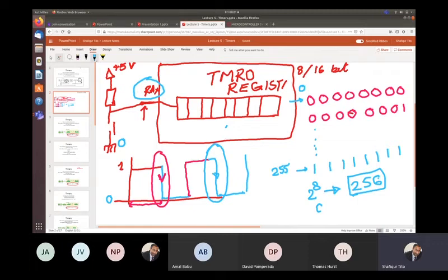That means state 1. Whenever I press this button, these two points will be connected, and this pin is directly connected to 0. So it will go back to the 0 state. Pressing this button creates a transition from high to low. This falling edge can be considered as an event for this register, and during this event the internal value will be incremented.